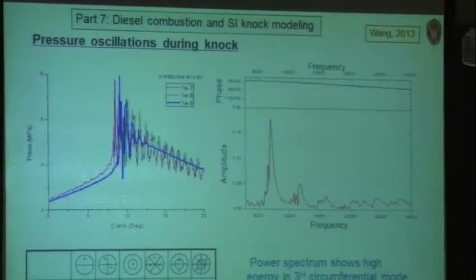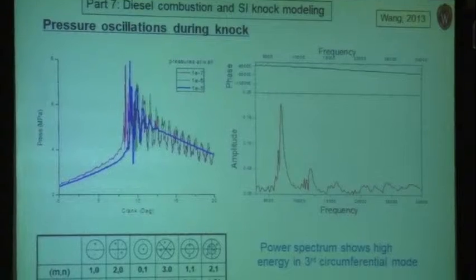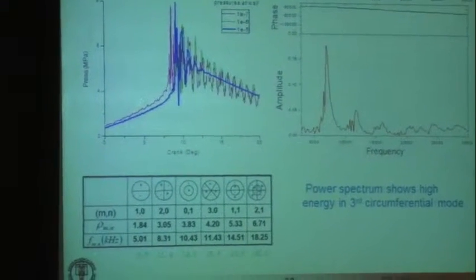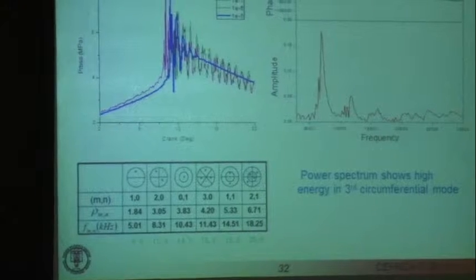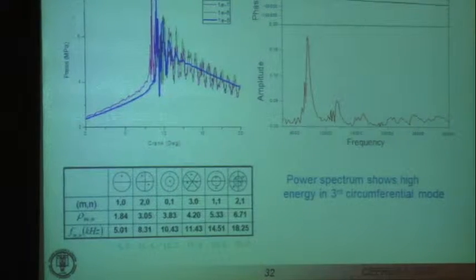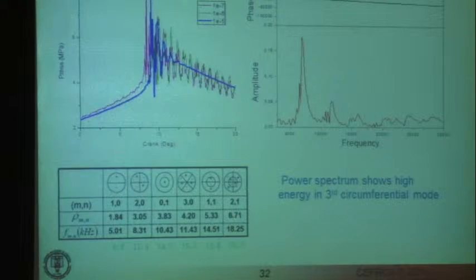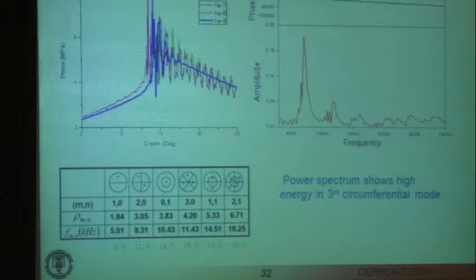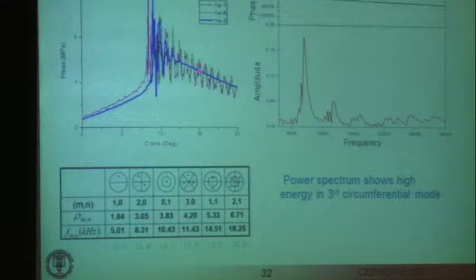If you do a calculation based on the estimate of the acoustic wave speed, the sound speed, and the dimensions of your mesh, you find that you need very, very small time steps in order to actually monitor a pressure wave crossing the mesh. So you see the time steps here all the way down to 100 nanoseconds in a simulation.